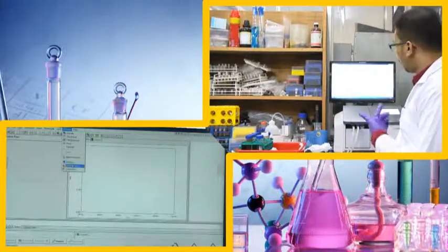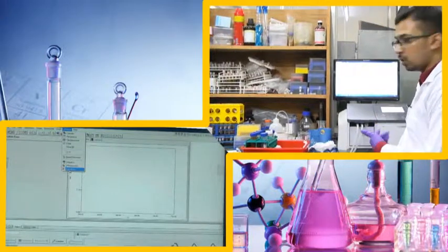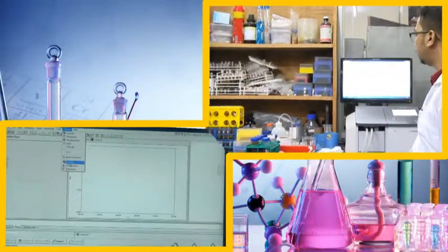Now, what we can see here in the software tool, this is the screen. Here we can see that this axis is the absorbance, and this one is the nanometer wavelength part. Now, for kinetic study, we need to shift this from absorbance versus wavelength to absorbance versus time. For that, we should go to window and select. From here we can see kinetics, photometric and spectrum. Okay. From here we can select this kinetics.